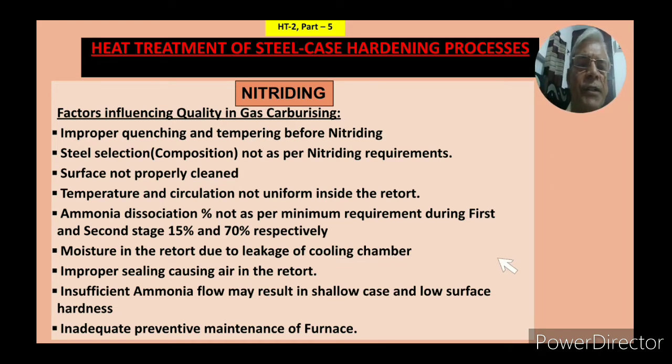Then insufficient ammonia flow may result in shallow case and low surface hardness. This is also for what you are using, flow meters and other things, that you have to give the proper ammonia which is required and the proper flow has to be maintained. Otherwise you will not get a good surface hardness if the flow of ammonia is not maintained properly.